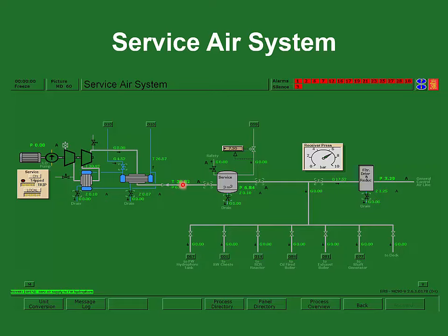Now again, you do have on these a crossover from the ship service, from your start air system. So if you were to lose your control air compressor, then your backup is off of the ship's starting air bottles. But you need to be conscious of that, because if this was to happen to you and you get an alarm for low ship service air pressure, you need to immediately be opening that valve to make sure that you do not lose control of vessel systems and have a blackout.